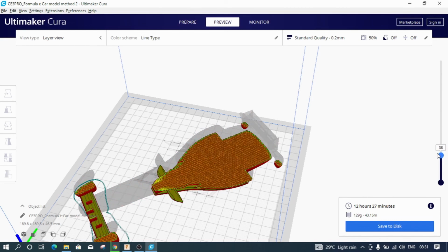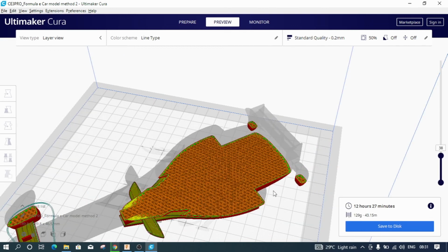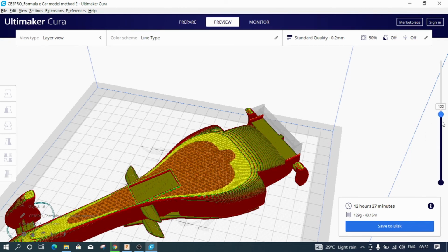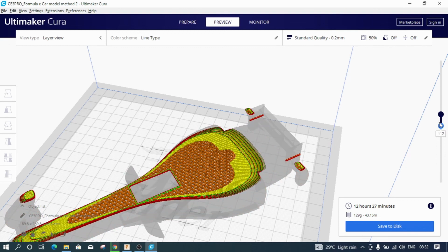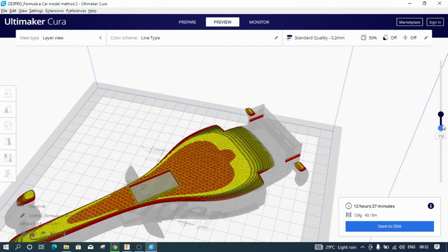As you can see, we have used a 50% infill, and the outer perimeters are fixed and internally there is some porosity. This is because we gave 50% infill. So 50% will be empty space and only 50% of your model will get filled up with the plastic. You can use these two buttons to understand how each and every layer is being built by the 3D printer.